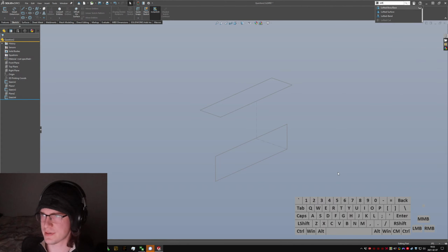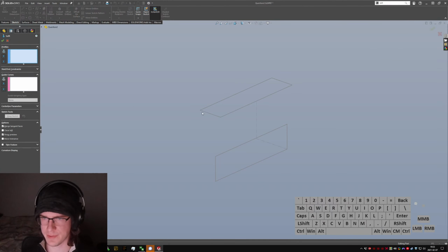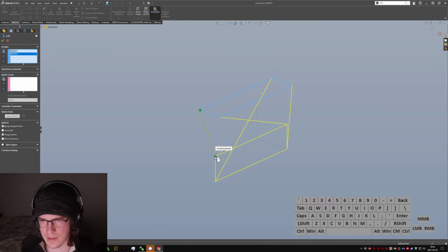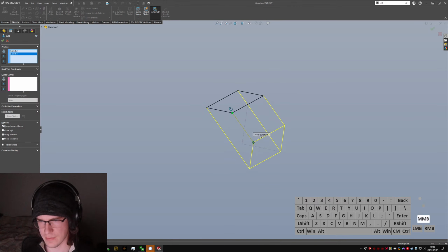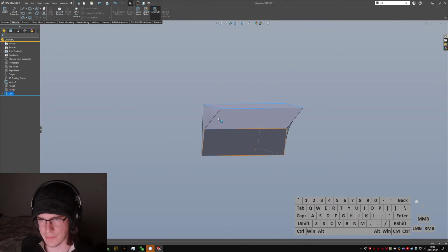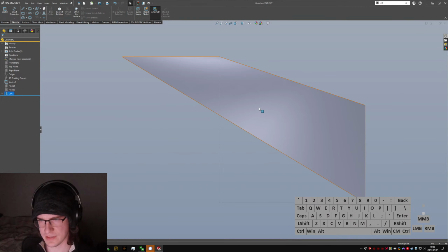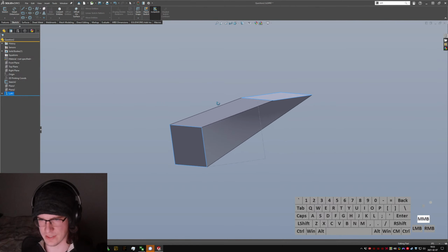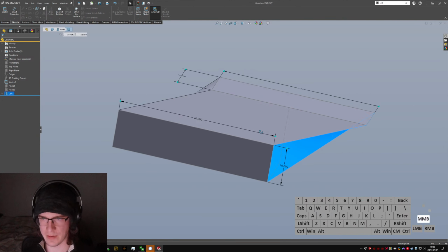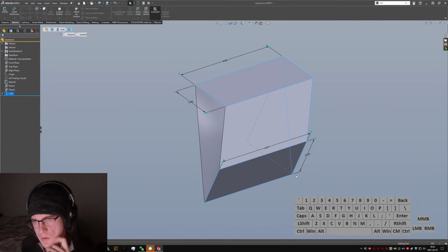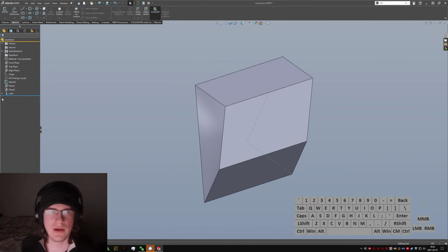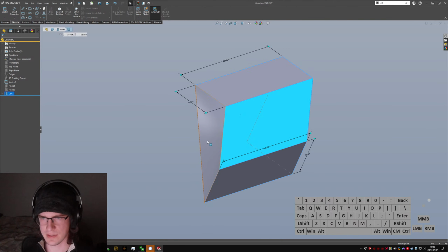So, loft, lofted boss, I'm assuming. That's profile, pick this guy, and then pick this guy. Those corners, oop, I picked the wrong corners actually, but you can drag these green guys around to tell it where you want those to match up. So, if we just leave it as it is, obviously this is somewhat unsatisfactory because it doesn't have the nice swoopiness. We can come up back here and it looks kind of all jacked up. These faces are curvy, but that's only by merit of the loft making them that way, or rather, necessitating that you have those curves to be edges for these straight lines and these faces.